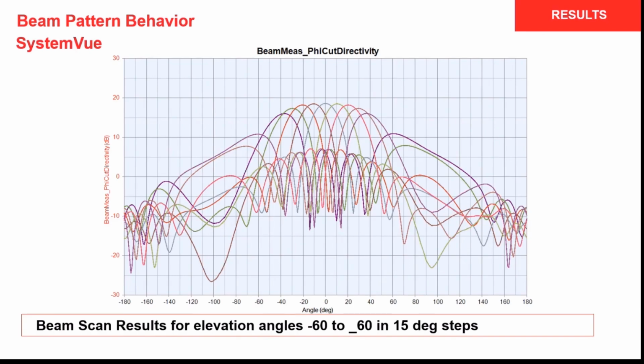The key here is choosing how to partition our designs. We wouldn't want to do all 16 channels of that previous design in a full electromagnetic analysis, maybe once as a final validation. But in the design process, it's not possible to run those simulations and iterate on your designs quickly. So by using system level representations of the phased array, but incorporating the accurate models of the individual components, you get the best of both worlds, and you can create very accurate digital twins of your systems while still incorporating all of the unique capabilities of 3D HI.